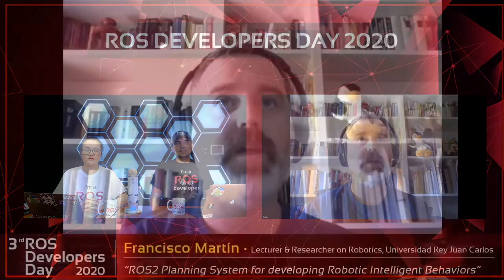Then we have a very interesting question from Jonas Moura. He says, how does PlanSys deal with urgent states, like for example, when a humanoid robot starts to fall while following a plan? Yes, that is a very good question, because PlanSys doesn't care about that. Because of the composition we did in skills, tasks, and plans, maybe this is something that the lower layer, the skill layer or the task layer, has to deal with. Not the plan.